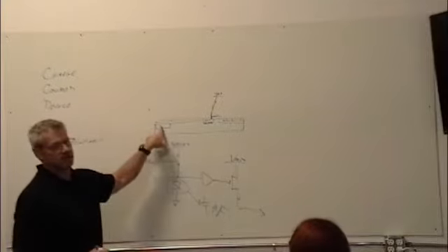If I've got a whole sea of these things out here, and I've got a wire coming to do this, a wire coming to do that, I've got to somehow bus all of these together. So usually I'll just use a transistor here to choose, and this will go to everybody in this column, and then they'll come out on another line, and I'll have a series of them down here. I'll multiplex them and choose which one I want to read. And all that obscures your image area.